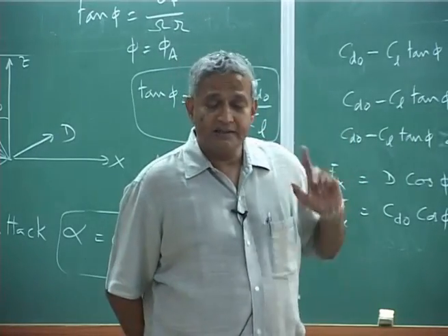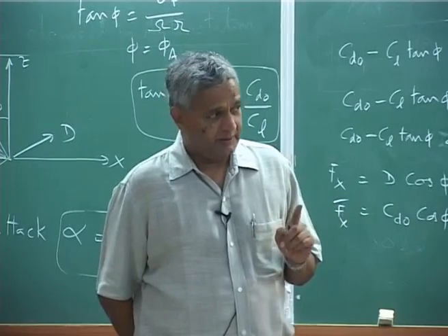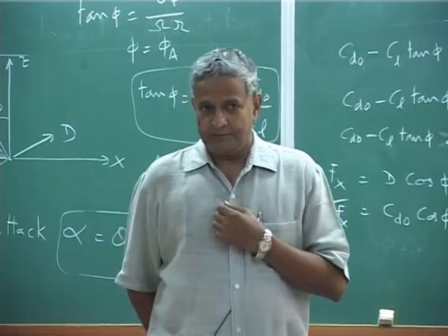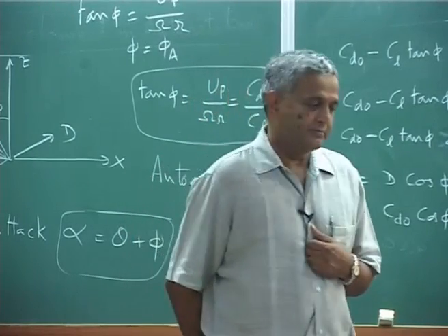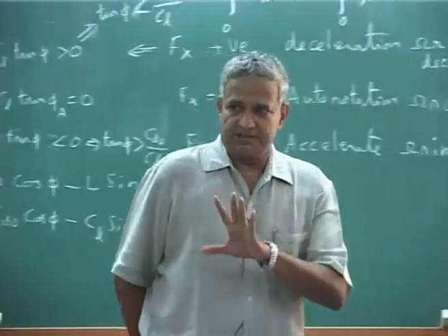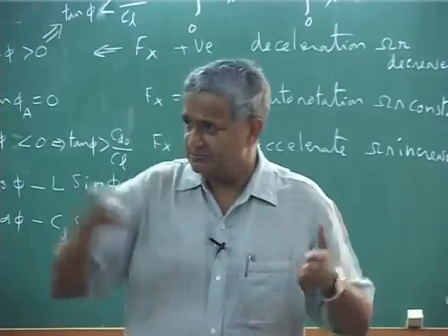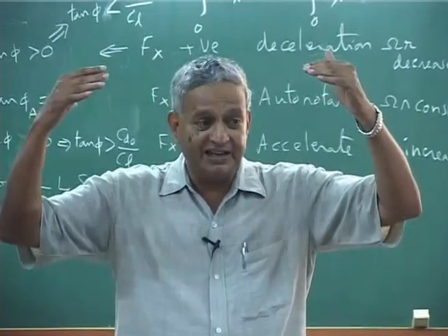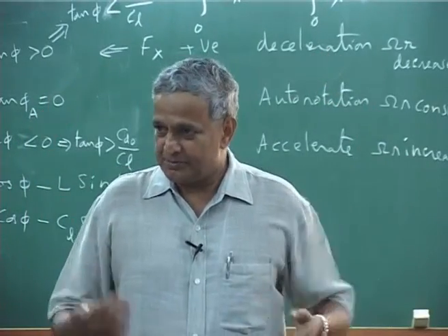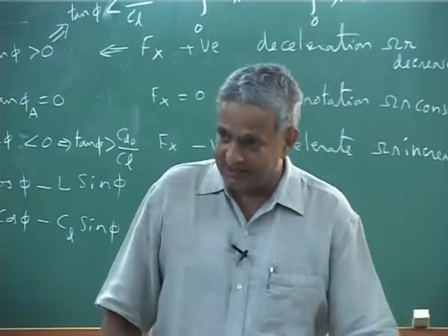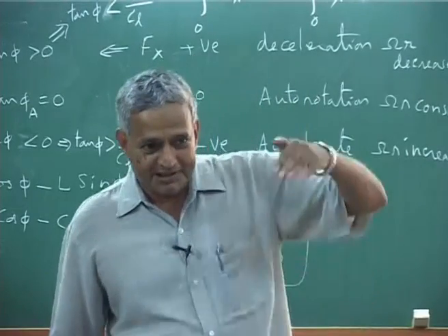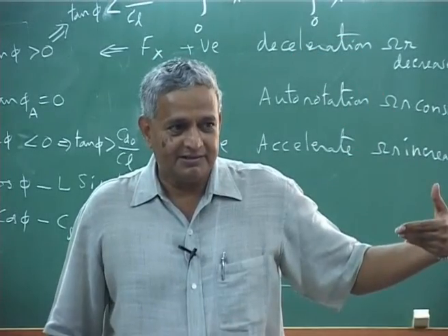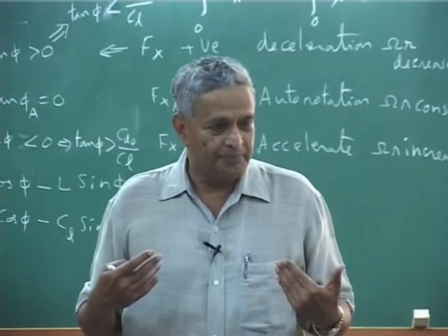And in auto rotation, another important aspect is the inertia of the rotor, because the rotor should have sufficient inertia. Inertia means mass into r square, because if it has a large inertia, it will not decay faster, because the pilot takes some time to react. You are operating at a higher pitch angle and the engine fails, immediately drag force will try to stop it.